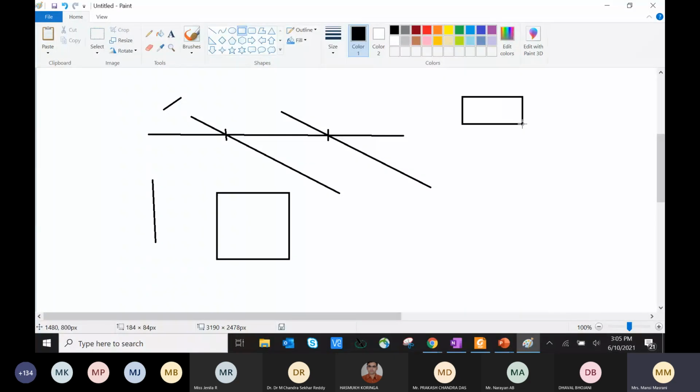Let me show it this way. This is how the via looks. I'm trying to draw it in 3D. You guys have to imagine something out of it. This part is going to touch the top metal layer, and this is going to touch the lower metal layer. This is just one via, the intersection between the top metal layer and the lower metal layer, and this is going to provide the low resistive path between the metal layers.